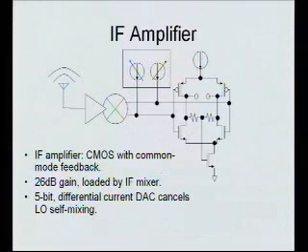Okay, so once I've gotten this far, here's my LNA and mixer combo. Now I need to gain it up some more, since I've come down to my IF. But before I can do that, I have a problem, which is that this is essentially still a direct conversion mixer. It's just that my signals aren't going all the way to DC. But there's nothing preventing other things from appearing at DC. And in particular, there's nothing preventing self-mixing of the LO from appearing at DC.